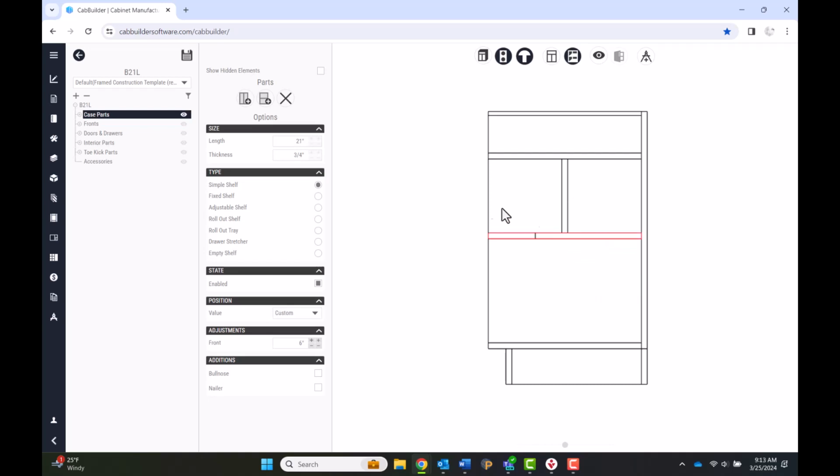The second is through the Position attribute. Select the shelf element and look to the position value. This represents the ratio between the space below the element relative to the overall vertical space that it occupies. 0% makes it flush to the bottom element. 100% makes it flush to the top. 25% puts it at a quarter of the way up, 75% the opposite, and 50% places it in the middle between the upper and lower boundaries.